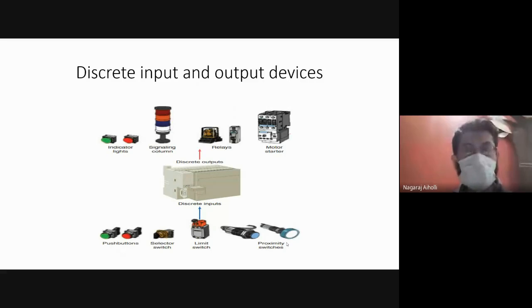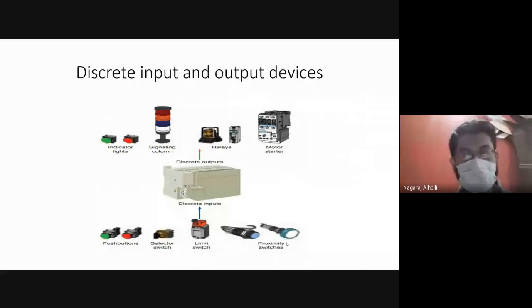Now how will you come to know that there is an input device? You will come to know when you bring that field device nearer to this proximity switch. Depending on the distance, the cutoff, that is a rating and specification that is maintained, based on the cutoff distance required, the proximity switch will operate. It will convert the given signal into an electrical signal, and that electrical signal will flow in the required circuit.